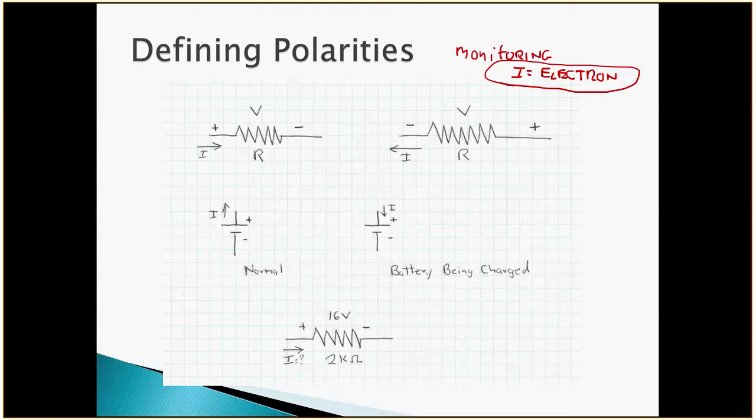And so what I'm going to show you is what is industry standard. For a load, a resistor, it cannot provide any energy. It can only eat energy. For this load, we are given definitions that as the direction of the current, as current enters the load, that's the positive terminal. The negative terminal is where current leaves the load, okay? So in this direction, I'm showing current, and I see a positive and negative.